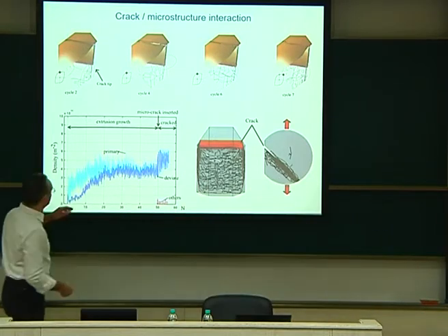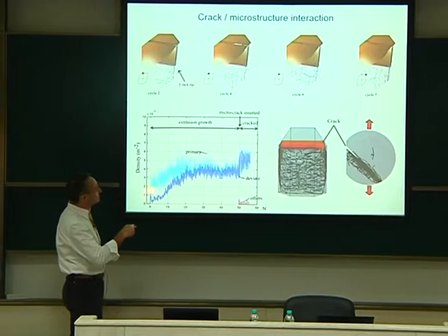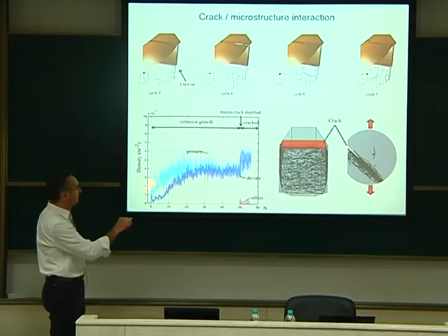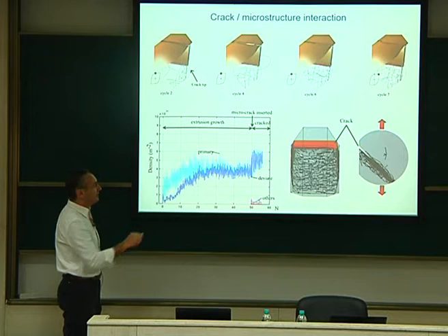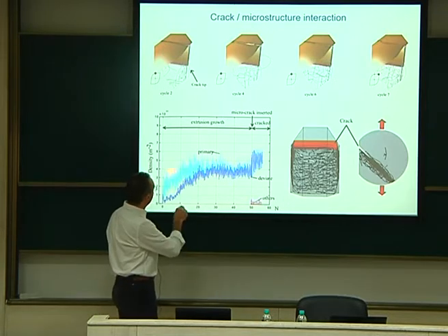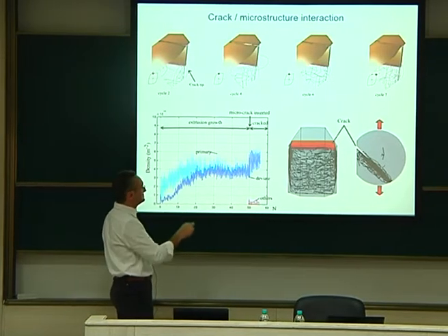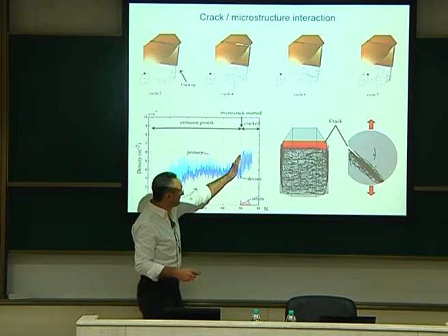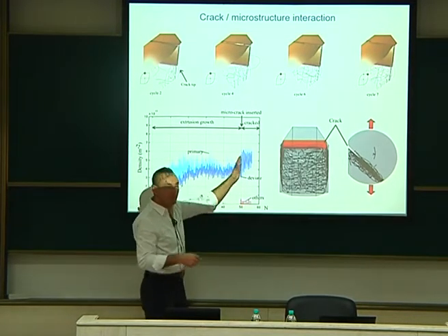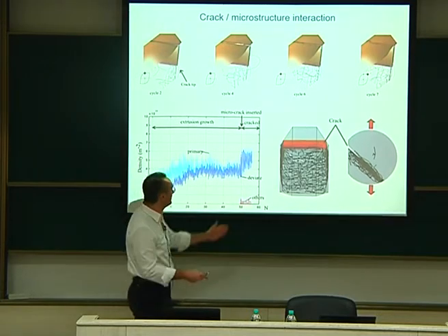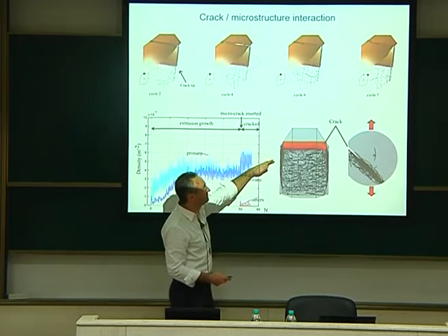So here, this is what we did. Here you see the dislocation density evolution for the two slip systems that I showed yesterday. So the primary one, the secondary one. So this is a mode 2 cracking. You can see that those two more or less tend to be the same. So there is a dislocation density which is equivalent. And at that stage, so after 50 cycles, now we introduce the crack. Of course, because the crack has to be introduced after the PSB is formed. So we put it here, and we see how it goes on.